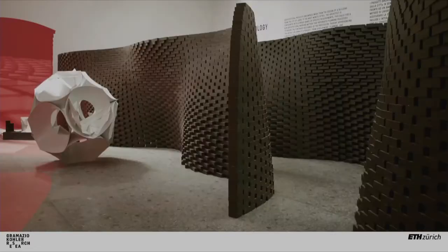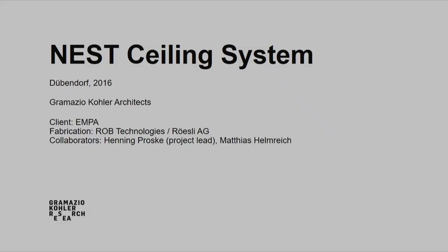And here you see that the difference to the winery is that here the brick wall becomes structural. So it is informed by structural logic. It's just 8 centimeters, paper thin in these dimensions. And there is no additional support structure needed anymore. And this is part of the beauty of this. So we're talking about the addition of identical parts.